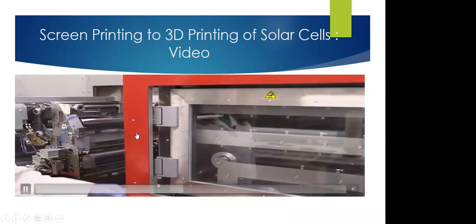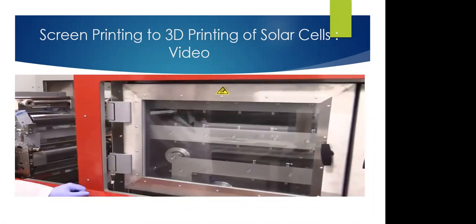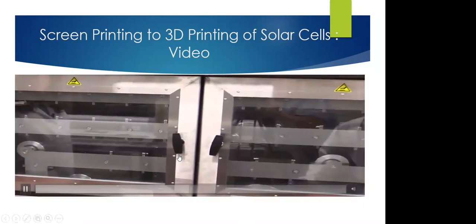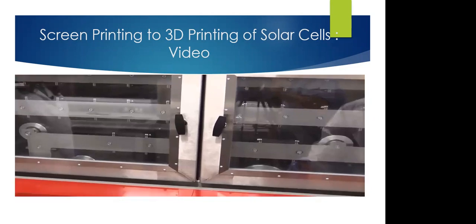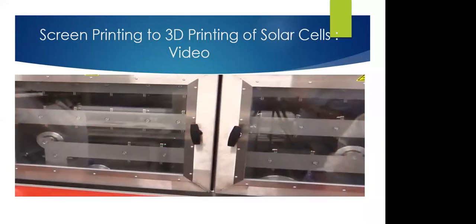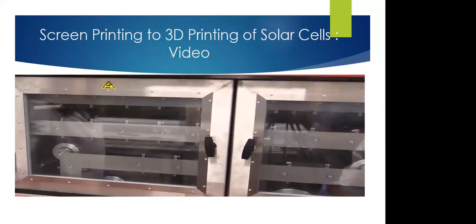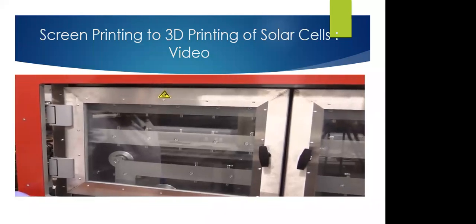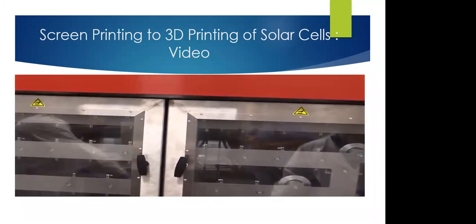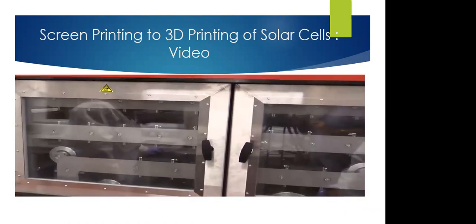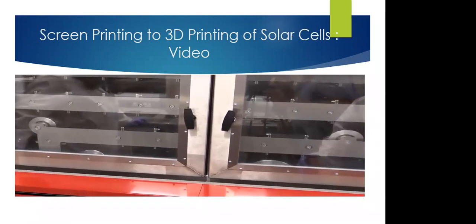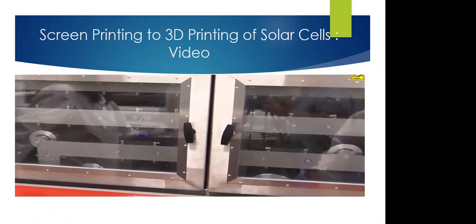After printing, you need to dry and anneal your films. So we move into our first oven. This is a 12-meter oven, allowing for residence times anywhere from 30 seconds up to 10 minutes. And we can run it from anywhere from 50 to 150 degrees Celsius. So in this oven, we take a multi-pass cycle through a spiral pattern to optimize oven residence time, as well as allow the film to maintain an upright position during the initial pass to prevent any runoff of your film.